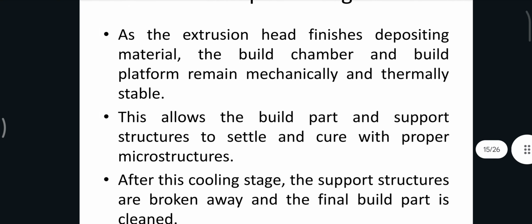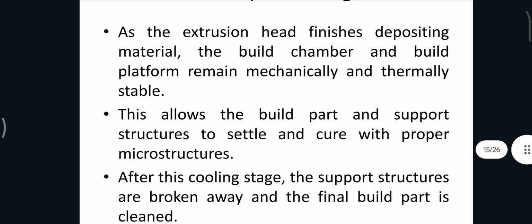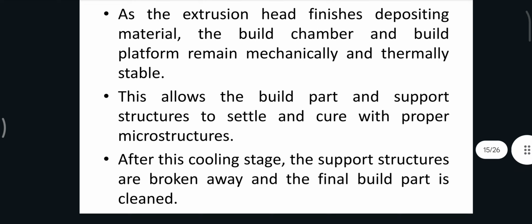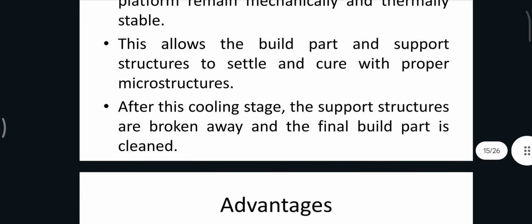As the extrusion head finishes depositing material, the build chamber and build platform remain mechanically and thermally stable. This allows the built part and support structure to settle and cure with proper microstructures. After this cooling stage, the support structures are broken away and the final built part is cleaned.